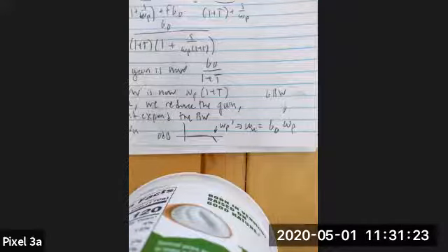I believe it's an approximation just because there's like a factor of 1 or something in the in-depth derivation. But this is a tool you can use to quickly approximate not only the unity gain frequency of an amplifier, but also, by dividing by a factor here or there based on the feedback factor, the effective bandwidth in different closed loop scenarios.